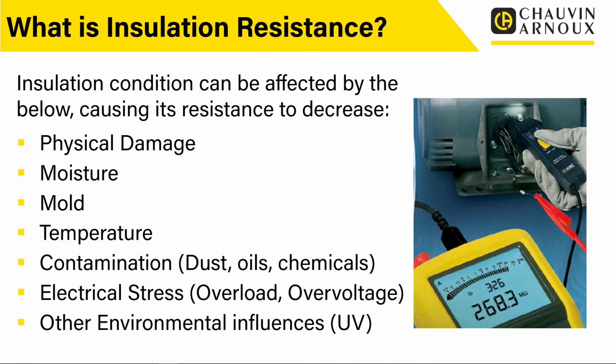There are other environmental factors that we need to consider, and a typical one that comes across quite a lot, particularly with PVC cables, is UV, ultraviolet. If we're using PVC cables outside, they will be exposed to ultraviolet, and ultraviolet can degrade that insulation over time. It's very common to see, if you've got the grey twin and earth cables outside, where they've been exposed to UV, that they get a white sort of coating on there. It's almost bleached the surface, and in extreme conditions you'll see it goes quite hard and brittle and crusty and actually starts to break down over time.